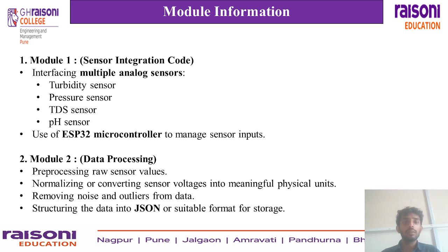The first module is sensor integration, in which we have integrated multiple sensors into the purifier, such as a turbidity sensor, pressure sensor, TDS, and pH. To control those sensors, we have used the ESP32 microcontroller to manage the sensor inputs and send them to the cloud.